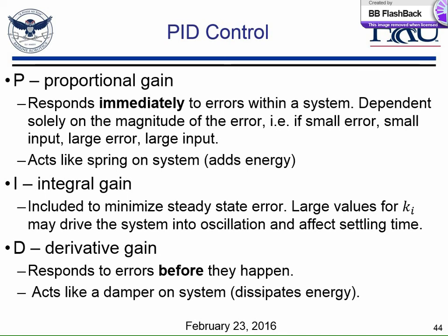We can actually make that a little bit better by incorporating a PI term. So we're going to add an integral term. What happens here is we're now going to have a faster response, but way more oscillation, but no steady state error. We include this integral term because it will actually kill out our steady state error as time goes to infinity. We also have a faster rise time, which is good, but we have a larger peak. We're going to have a longer settling time as well.